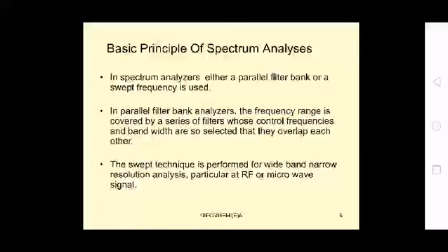And the second technique that we are using, particularly at large frequencies, that is radio frequencies and microwave frequencies, we cannot place all the filters, as it would be very costly. So that's where we are using the swept technique, which is used for wide band, narrow resolution analysis. So when we are going for the wide band narrow resolution analysis, we are going for the swept technique, which is mostly used at RF or microwave signals, radio frequency and microwave signals.